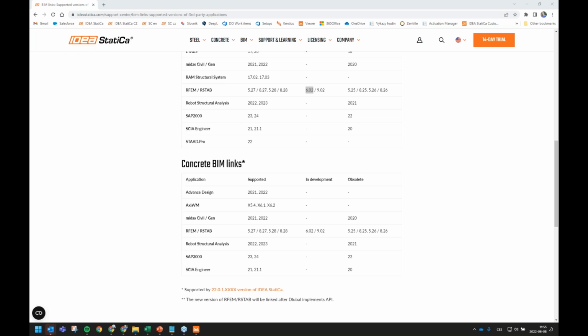For cases somewhere in between, if you are not sure if it's more of a pinned connection or a stiff connection, then it's a little bit more tricky. You can always run our stiffness analysis and decide.